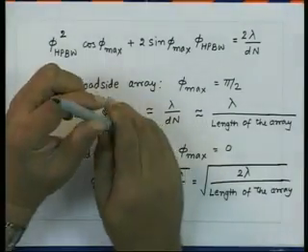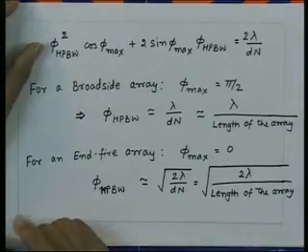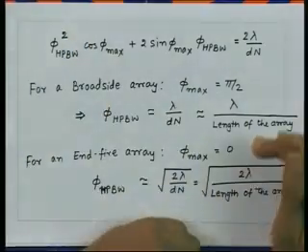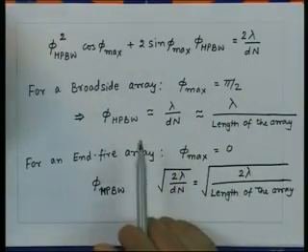So, when the beam is in the broadside direction, the half power beam width is inversely proportional to the length of the array, or for given inter element spacing it is inversely proportional to the number of elements. So, the number of elements essentially plays a role in deciding the angular zone in which effectively the energy goes.